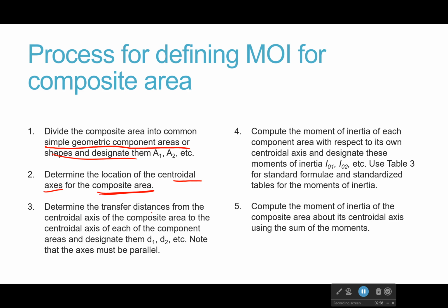So once again, all these centroidal axes and centroidal locations for these various basic shapes, you've got to remember that even though, yes, you know that for two boxes it's right at the center, this is going to have some composite centroid, which would be right here. That's the big centroid. And you want to know the distance from that point to everything else. That's your reference. That's your origin now. And that's where you're going to get d for each of these. And you're going to compute the moment of inertia for each of these. And then finally, add them all together.